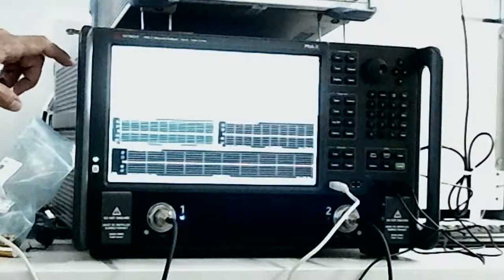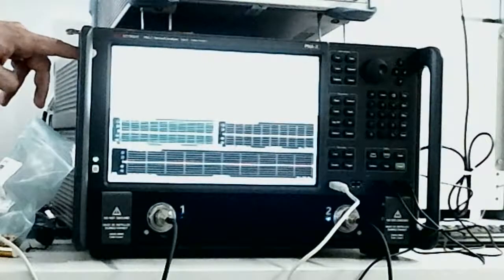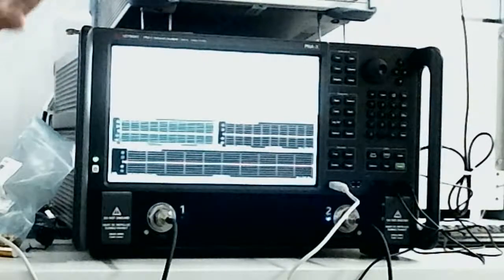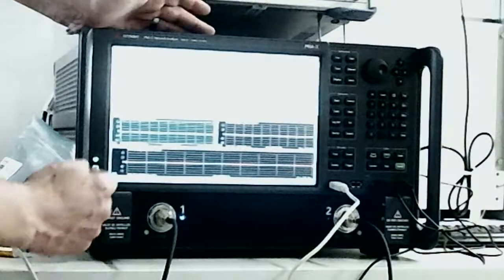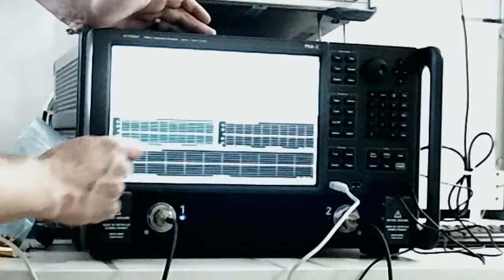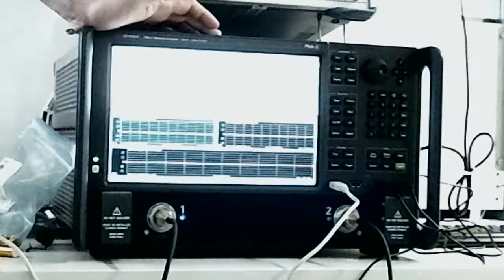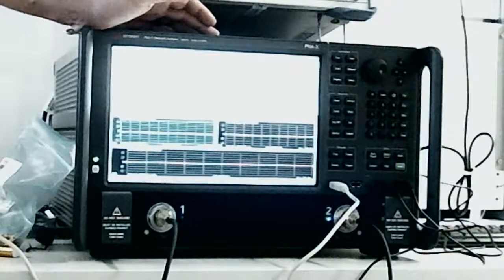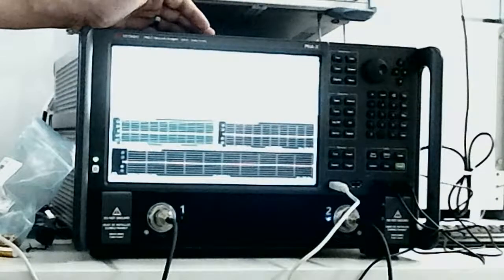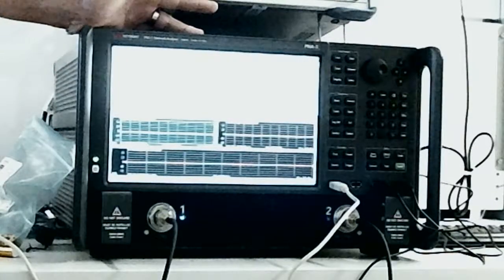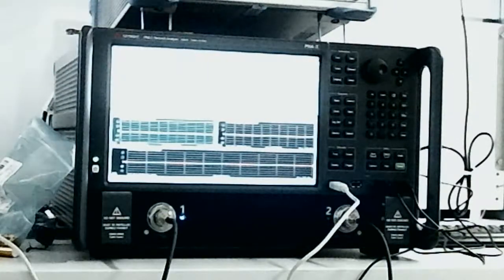So under cal all, you'll see it says, okay, channel 1, 2, and 3 are all different standard measurements. They're all 2-port measurements, right? We can go next. It says include power calibration, and it says true. The reason it defaults to true is because these are power sweeps, so it's going to say you should probably do a power cal. Okay?